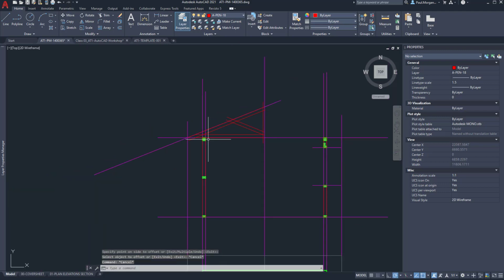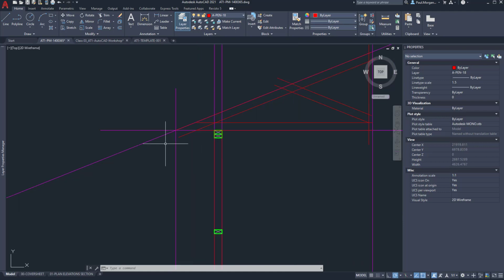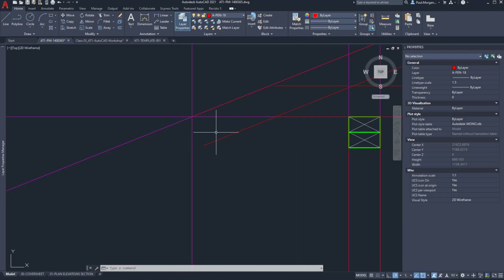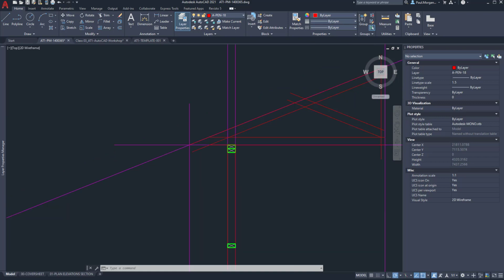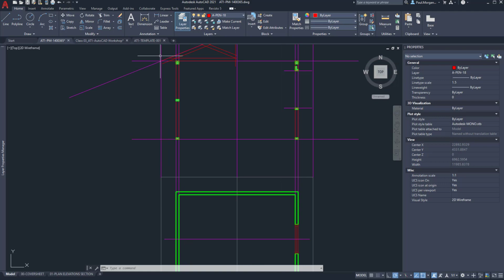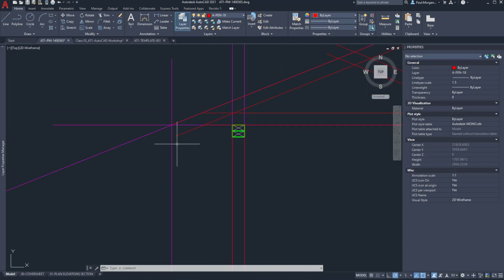go the other way. So at the moment this looks like, again, just a whole lot of lines just smashing everything all over the joint. We just need to clean some of this up now. So what I am going to do is I'm going to use another tool called extend, and what we need to do is get this line to meet up with the edge over here. So, which is our guideline, that is our roof overhang. You can see our roof overhang there, and our bottom chord of the truss needs to protrude out and get to this line here.